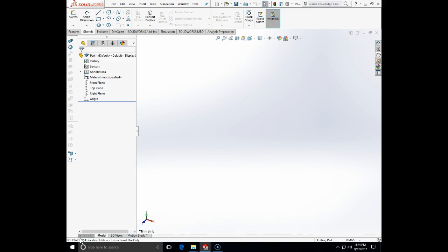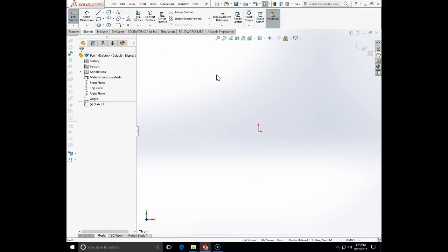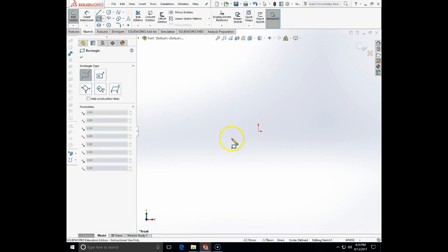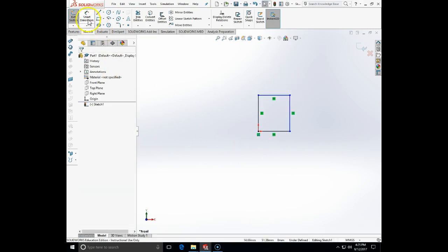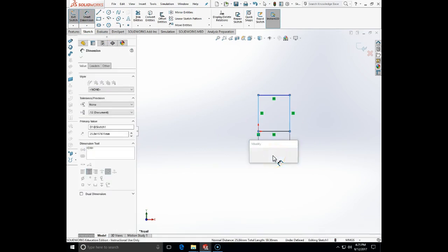So today we are going to start with an introduction to the bottom-up assembly, and we are first going to do the basic exercise 5.2 at page 299. For that exercise, we are going to start with a drawing in millimeters. I'm going to make a little L-shaped bracket, which is 80 by 80 by 80, and the L is 40 by 40. I will make this L-shaped bracket by first making a single rectangle, a square actually, of 80 by 80 millimeters.